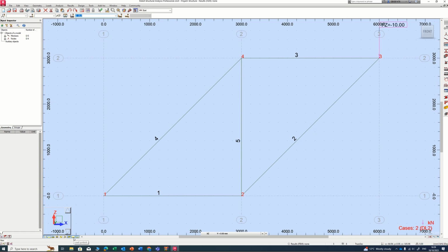So let me see the load symbol in here. So yeah, I need to press the load symbol in here. So let's click on that load 1. So make sure that this one is switched on. So this one load symbol switch on, switch off, switch on, switch off. Oh, sorry, switch off, switch on. Okay, and then we can change to that load case 2. Then you can see this loading has been applied properly to these structures.